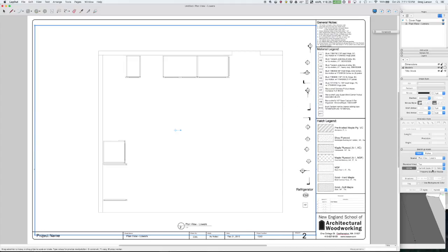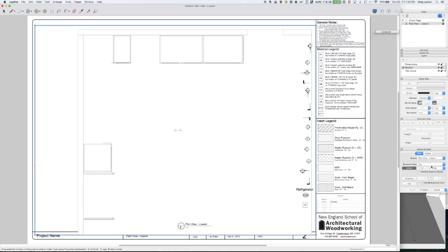And the scale that it's pulled this in at, if I go back down here, it's a top view, it knows that. Scale is 1 to 10.1.562. That's not really a handy scale for me. So I might choose something that's more standard. That might be just about workable for this view.